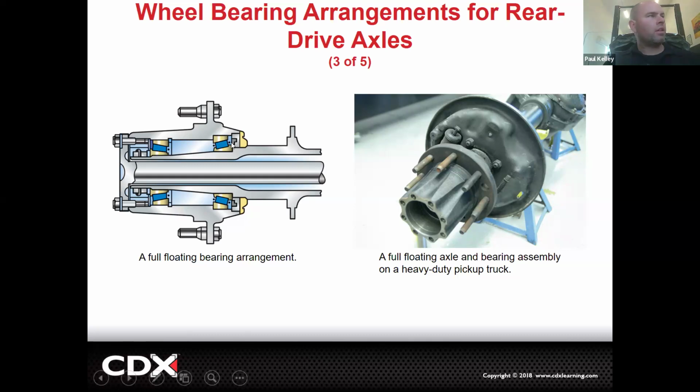If this vehicle was on the ground and I were to take these bolts out, do you see right here how all these 8 bolts are out? You could slide the axle out of this one and you could even still have all the weight on the vehicle. The axle is just floating. It literally just drives this hub clockwise or counterclockwise because it's splined into that center section. The axle itself, the axle shaft, holds no weight, supports absolutely nothing. It just makes it go or no go.